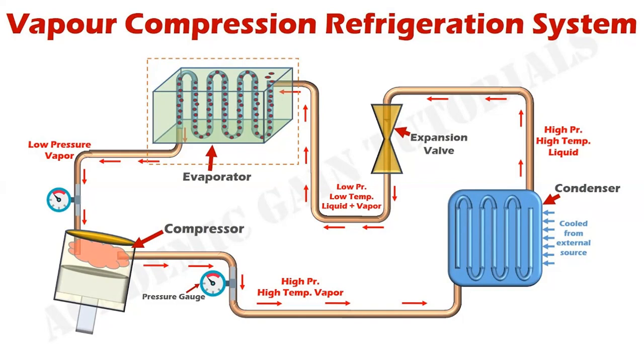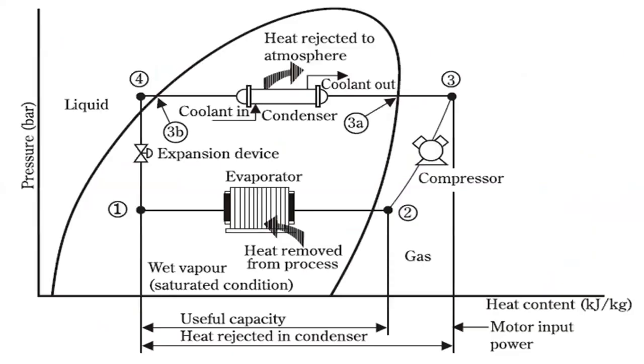The refrigeration cycle can be broken down into the following stages. From 1 to 2, low pressure liquid refrigerant in the evaporator absorbs heat from its surroundings, usually air or water or some other process liquid. During this process, it changes its state from a liquid to gas, and at the evaporator exit is slightly superheated. Then from 2 to 3, the superheated vapor enters the compressor where its pressure is raised. There will also be a big increase in temperature because a proportion of the energy in the compression process is transferred to the refrigerant.